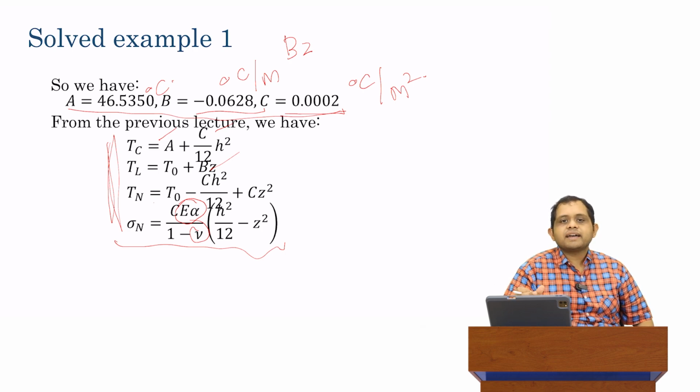In general, in design, you won't know the exact values of whatever we are trying to calculate a priori. You're going to have to make some assumptions. And then later on, the assumptions can be checked to see whether any significant deviation from the design happened. So in this case, we are not given E, alpha, and nu, which we need to calculate these eigenstresses. So we're going to make some reasonable value assumptions on what they are.